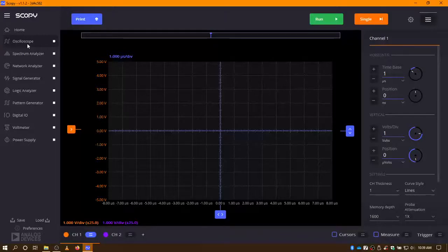Again, much like the signal generator, that does not mean you can measure a 25 megahertz signal with this device. Rule of thumb, and it's the same rule of thumb that you would use with a regular full oscilloscope, is you take that bandwidth, in this case 25 megahertz, and usually any oscilloscope will be good for about a third of that.